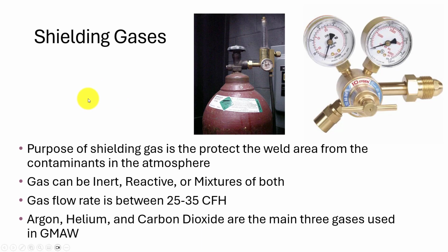Let's talk a little bit about shielding gas. Now, if you're going to be welding in a weld shop, you're probably going to have to do full-on high-pressure bottle training before you ever weld, because these things are up to 3,000 and 4,000 psi. And if you knock the head off this bottle, or you open this valve stem and you're standing in the wrong place, these regulators can have a tendency to break over time with the impact of that pressure hitting.